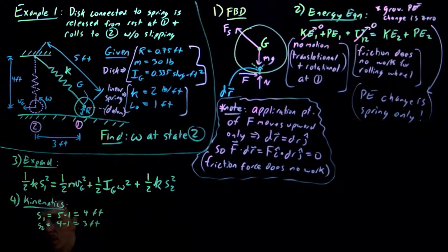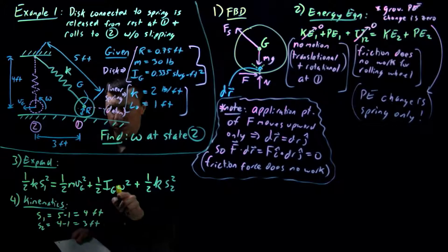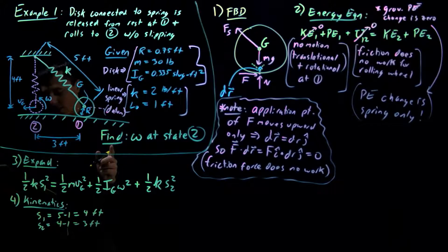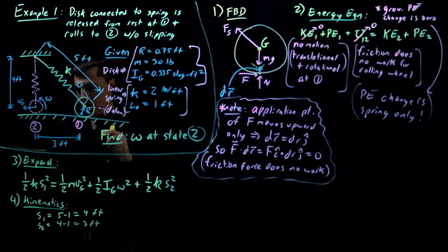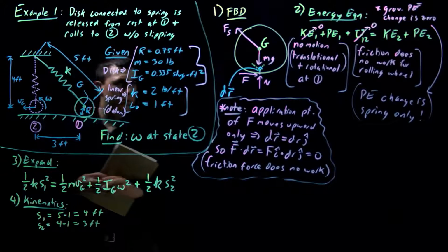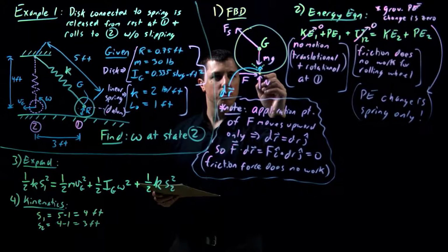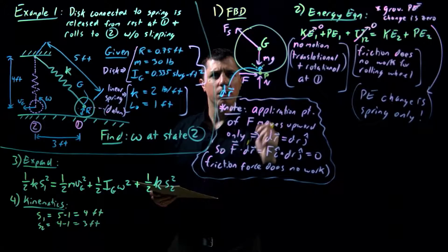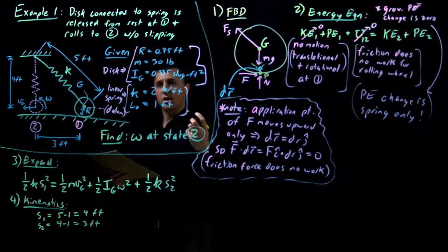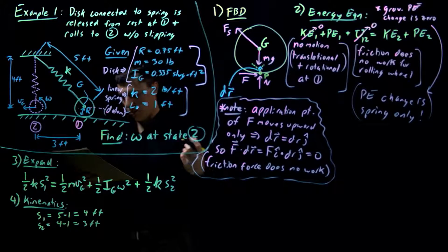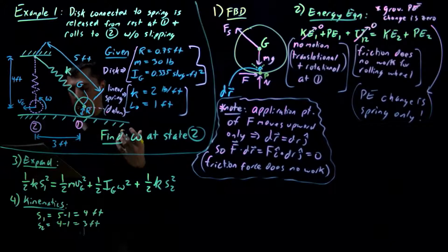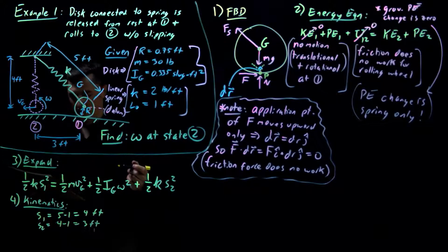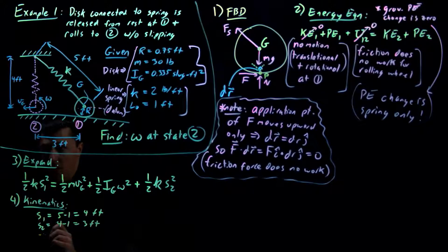Now for that relationship, vG in terms of omega, just notice this is a rolling wheel, and point P down here, let's put this application point, P. Point P is fixed. So we could do that analysis of a rolling wheel from that fixed position. Regardless, we get vG moves with respect to that fixed position at minus r omega.